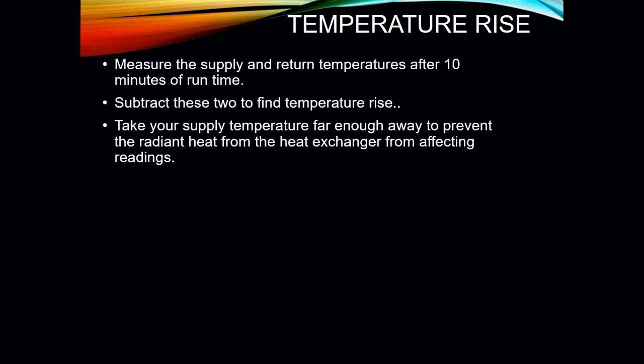Okay, to measure our temperature rise, you have to measure your supply and your return temperatures after 10 minutes of runtime. The reason why we say 10 minutes of runtime is because we need the system to have enough time to warm up. We need the heat exchanger to get to the highest temperature that it's going to be at in order for us to see what the system is actually doing. So to take that temperature rise, you have to subtract those two readings.